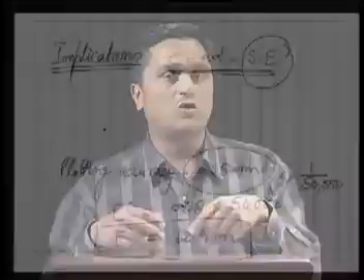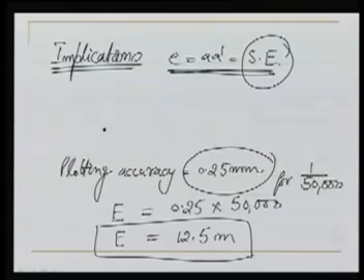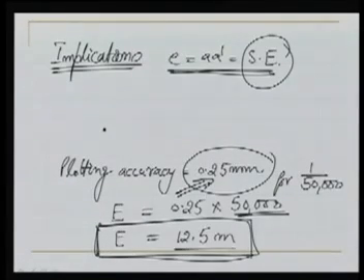So whatever the error we do on the ground corresponding to this dot is not a problem. Corresponding to this permissible plotting error, if you are working at a scale of 1:50,000, we find the value of permissible centering error is 12.5 meter. So you can miscenter your plane table by 12 meters, no problem. Still you are plotting within the plotting accuracy.